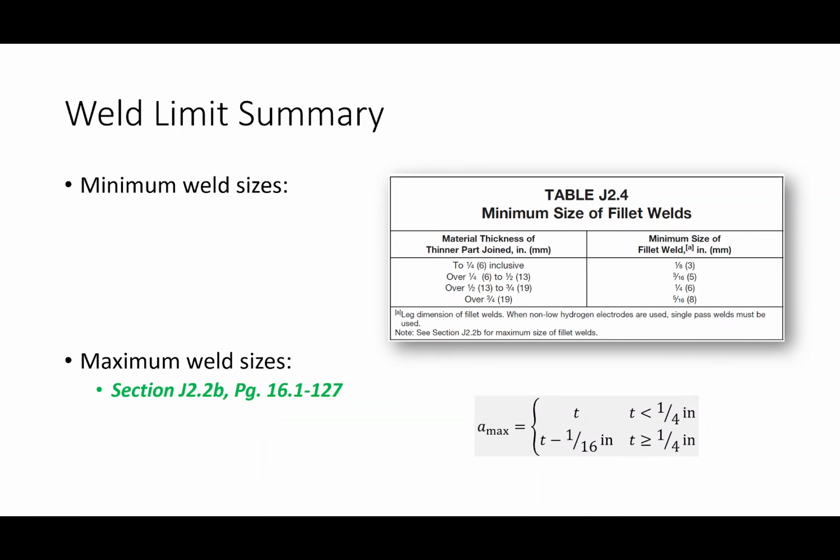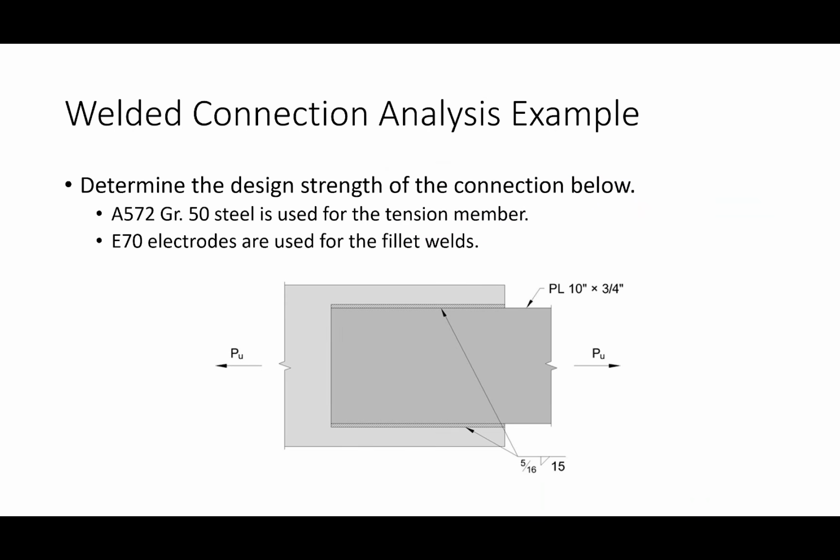And the reason why that's important is that the shorter the weld length, the shorter amount of time it takes to deposit that weld, okay? And that means less time in the fabrication shop, less money you're spending on labor in order to generate that connection, okay? Now, there are some caveats to that, which we'll talk about next time, okay?